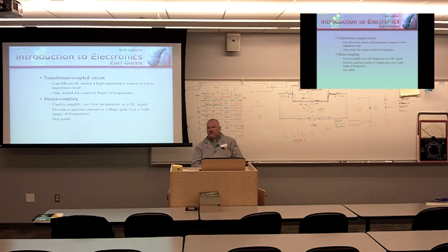Because unless you're matching the impedance, you're not coupling the maximum power from the source to the load. Now, sometimes, especially with an audio system, how often do you ever push it to the limit where you really want to do that? But still, if you don't, you're losing energy. You're losing energy, and efficiency is what it's all about.